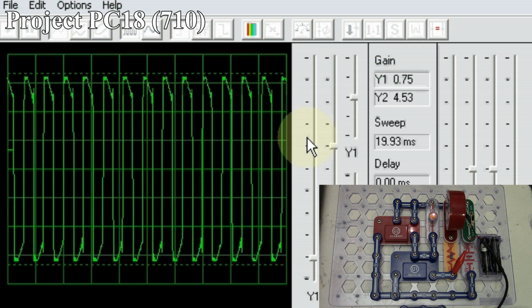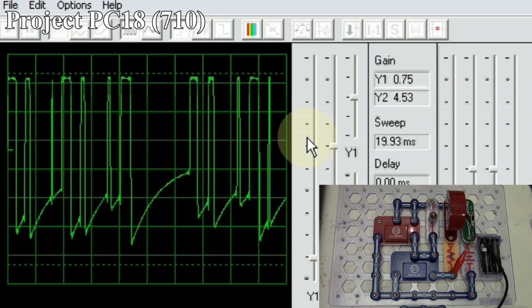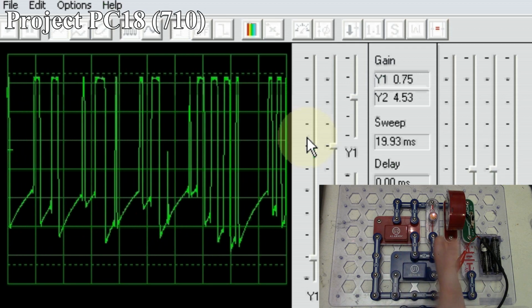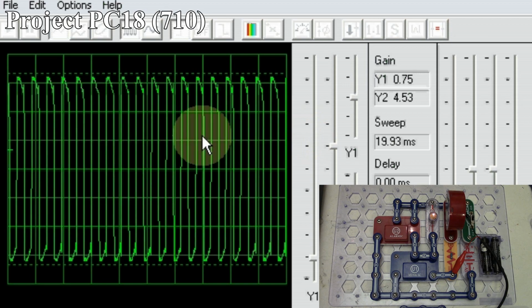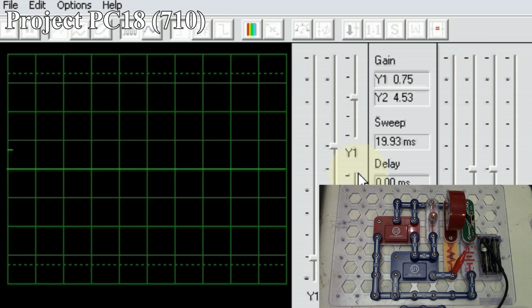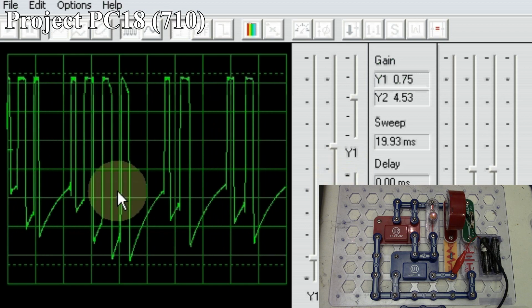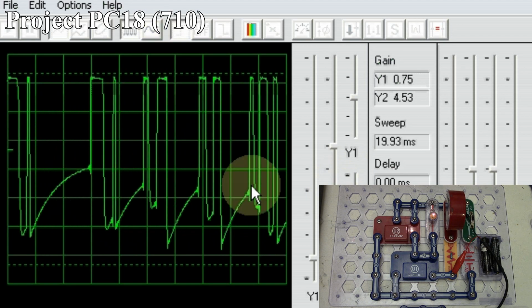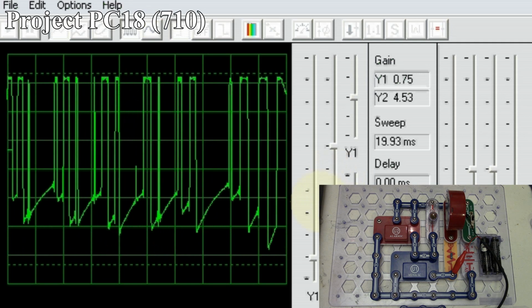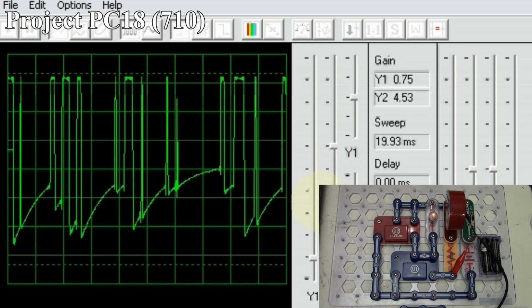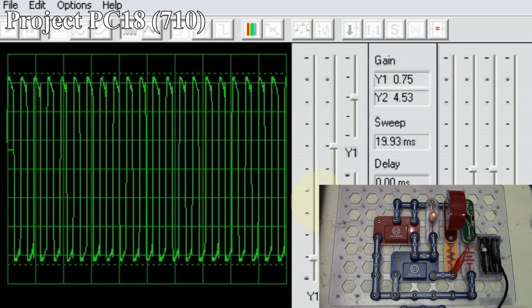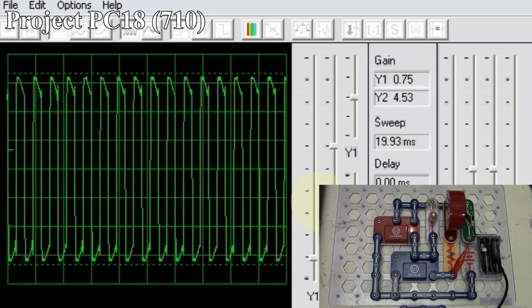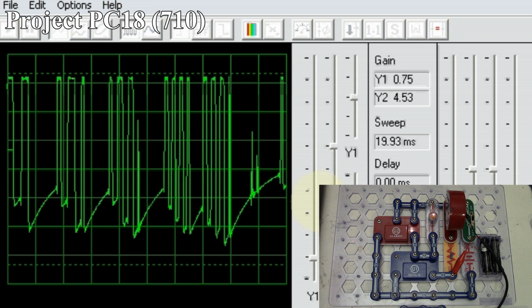So again, we're seeing the signals of the alarm IC and music IC kind of being interleaved, switching between each other. So the signal here that's got the spacing between it with a couple peaks is of course the alarm IC, and then the music IC is the one that has the constant peaks here going up and down. And because the alarm IC is also driving the music IC, it's periodically interrupting the music IC's playback.